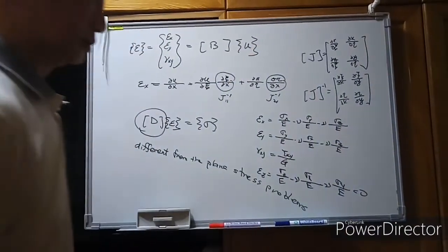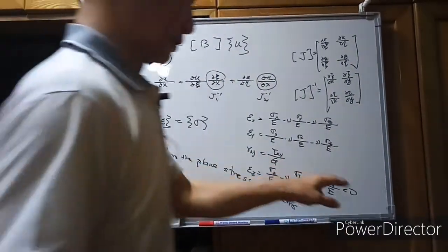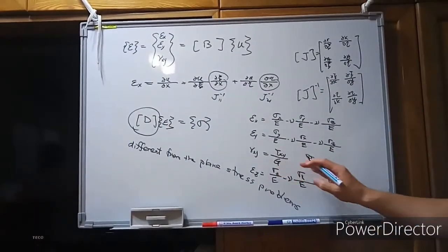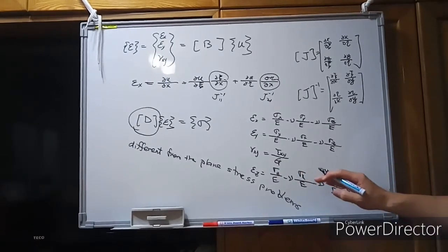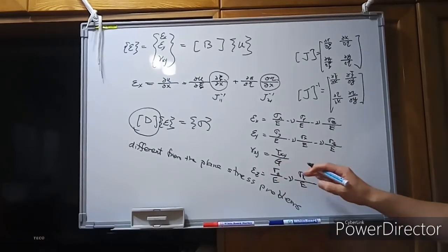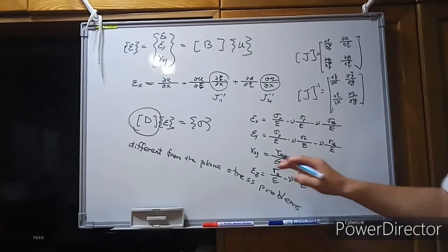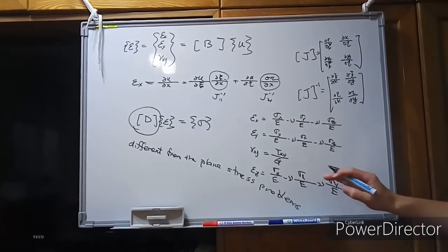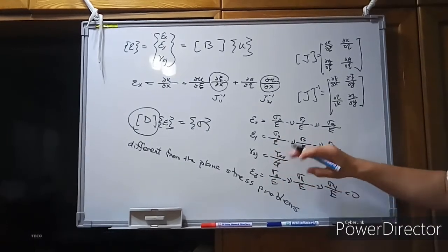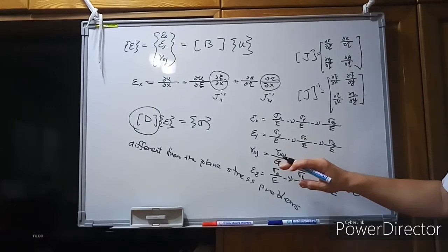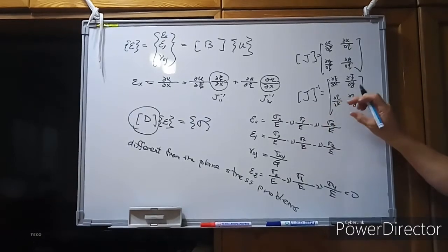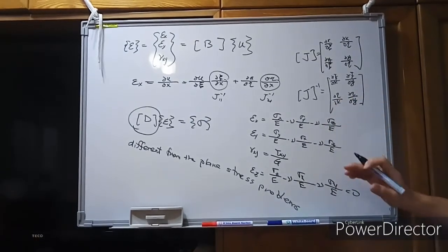we know this term should be equal to 0. If we take the fourth equation, then we can replace the sigma z by functions of the sigma x and the sigma y. Usually we will solve the fourth equation first to get the expression for sigma z. Then you need to replace the sigma z into the first two equations.